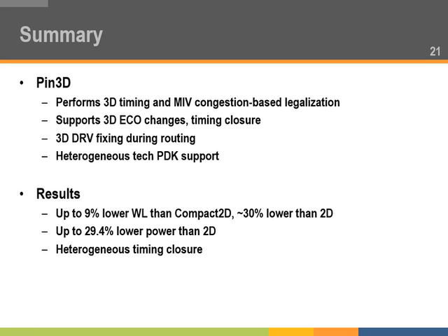As a quick recap, we have seen how Pin3D performs 3D timing closure, routing, and legalization. We also see that Pin3D gives us much better timing benefit compared to 2D design, and also power benefit. We saw how Pin3D can be used to optimize a heterogeneous 3D design. This applicability to heterogeneous 3D ICs is exciting and useful, as heterogeneous 3D ICs can try to alleviate some of the thermal issues and also try to improve the power benefit of 3D ICs and expand the circuit design horizon even more.